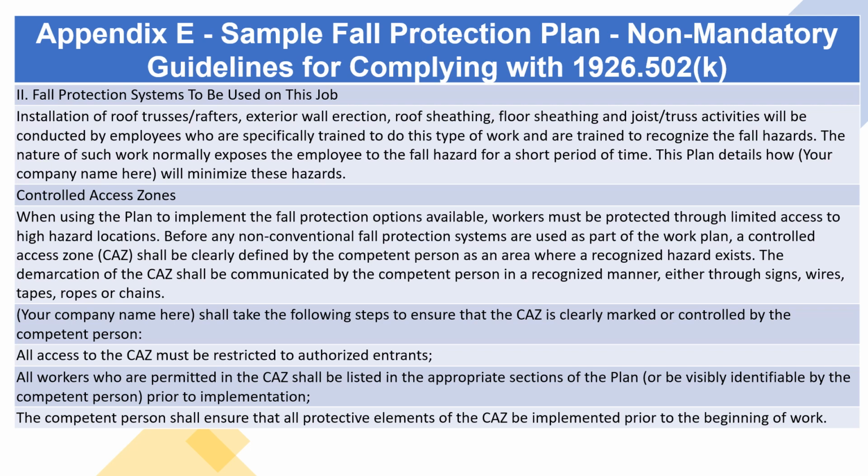All access to the CAZ must be restricted to authorized entrance. All workers who are permitted in the CAZ shall be listed in the appropriate sections of the plan, or be visibly identifiable by the competent person, prior to implementation. The competent person shall ensure that all protective elements of the CAZ be implemented prior to the beginning of work.